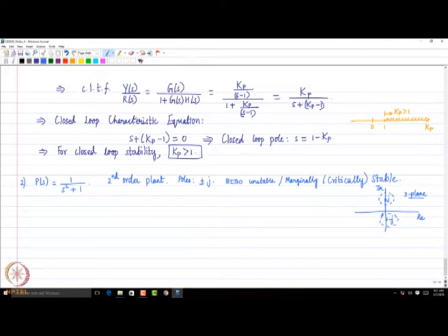Depending on my luck, sometimes a pole can be marginally in the right half plane, but still it's in the right half plane. The moment that happens, obviously the system becomes unstable. So in practice, due to these reasons, we do not want to place any poles on the imaginary axis by design.